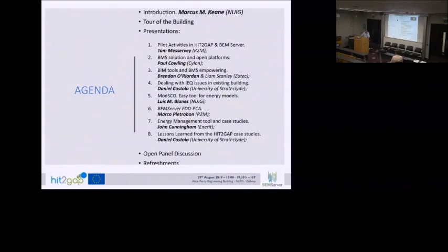What we want to do is look at the likes of our building manager here in this building, the guy called Dalton. How does he interact with the building in a way that he knows that that air handling unit, such as the one performing here, as you can probably feel, is a lot cooler than it should be? That's largely down to the fact that it's probably expecting an occupancy of about 100 people here, and probably for a period of 1 hour or whatever else it might be. So we're trying to figure out, in terms of the actual design intent, what is the gap between the design intent and the actual performance?